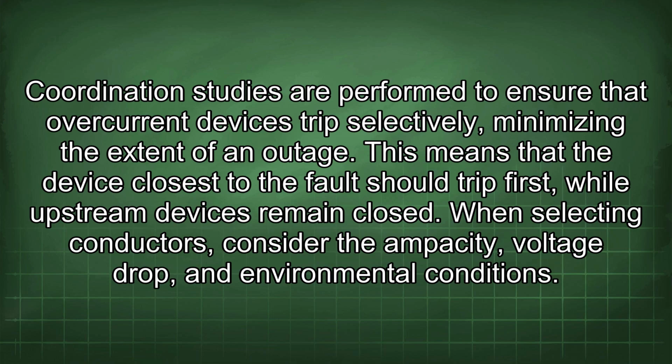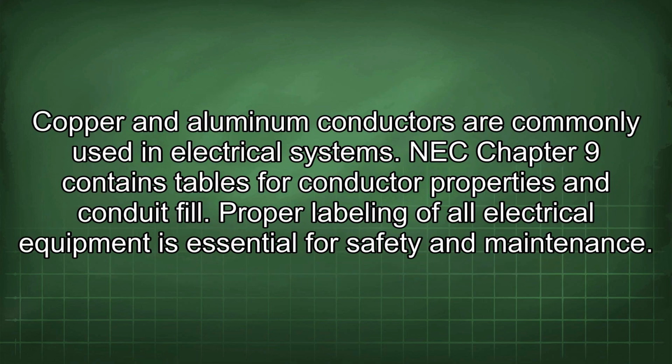When selecting conductors, consider the ampacity, voltage drop, and environmental conditions. Copper and aluminum conductors are commonly used in electrical systems. NEC Chapter 9 contains tables for conductor properties and conduit fill.